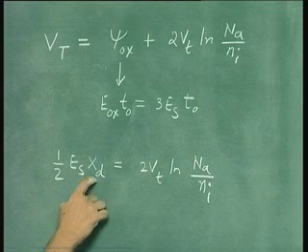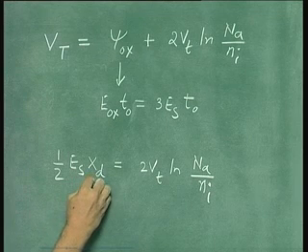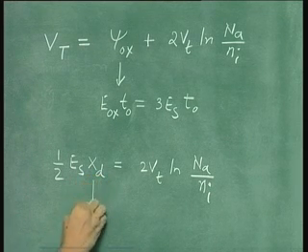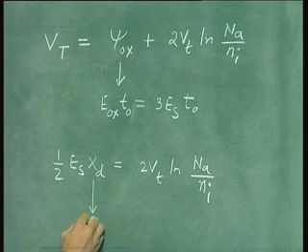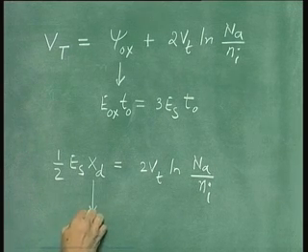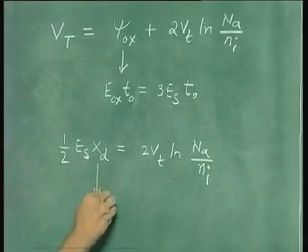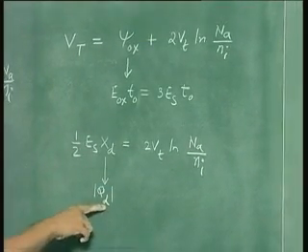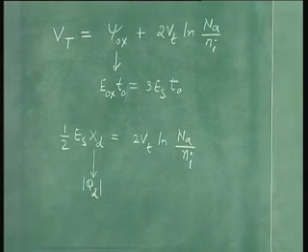Now this xd we can again write in terms of the charge. So this xd is nothing but the depletion charge, which we denote as Q suffix d. We are putting a modulus because the depletion charge is negative. What is the depletion charge?